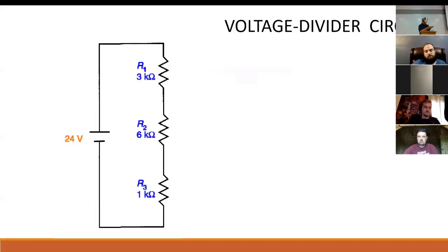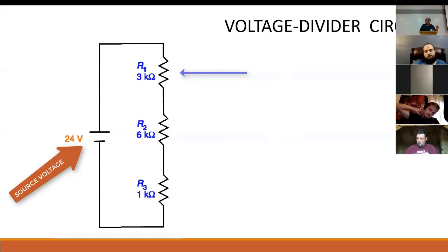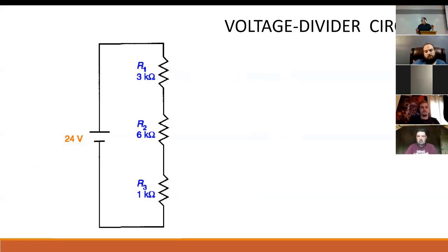All right. Okay, so the voltage divider. One of the characteristics of a series circuit is that the source voltage for that circuit is divided proportionally among all the elements, or all the loads, or all the resistors, however you want to think about it. And think about it maybe like this. If I've got a 100-pound weight and I'm sitting it on a 2x4, all of that weight is distributed among all the things that are bearing it.